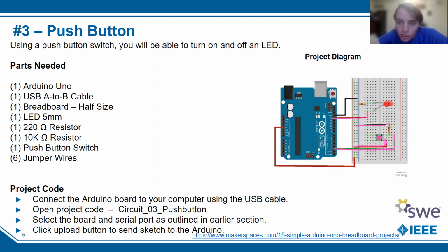And then that LED is connected back here to ground, and that's going to go back to the Arduino. So that input coming back through pin 2 from when you push the button is going to be sent out to this LED here to tell it to turn on. And when you're not pushing it, it's going to tell it to turn off. I got you. That makes sense. So for the push button, yes.